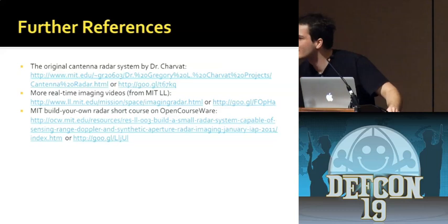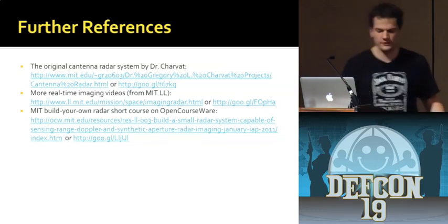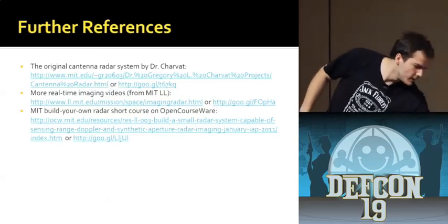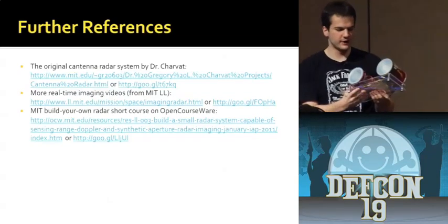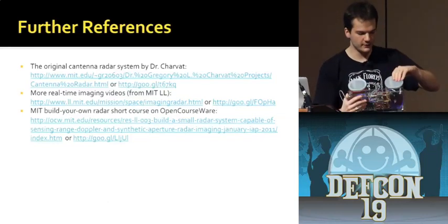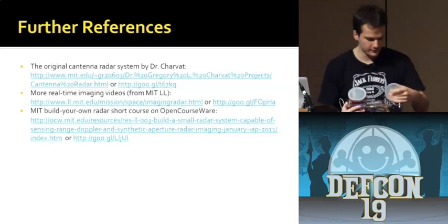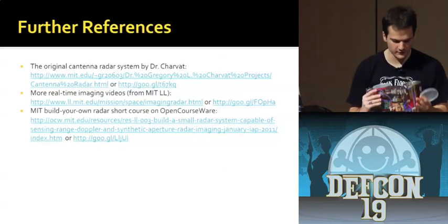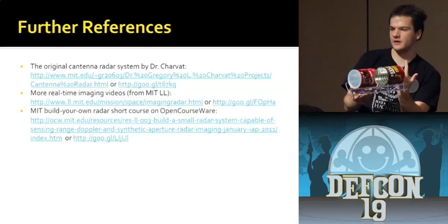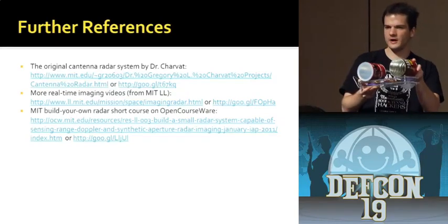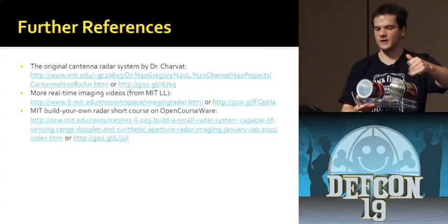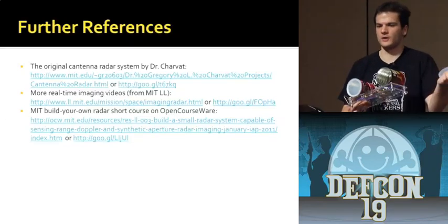Well, the coffee cans are somewhat directional. He asked why coffee cans as opposed to a different type of antenna. The coffee cans are fairly directional. They were really cheap because they're coffee cans and we had them anyway. It's going to be hard to see inside this thing, so you might have to come back later and see. The way this works is there's an SMA connector in here, and there's a little wire being fed into here. So this is basically a waveguide port. It's an adapter from that little feed antenna to this larger waveguide. And then it's basically a crappy directional antenna.